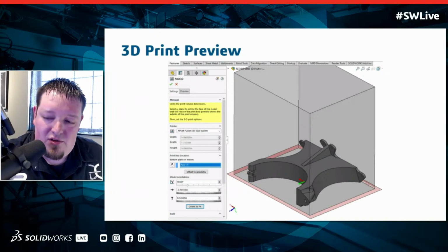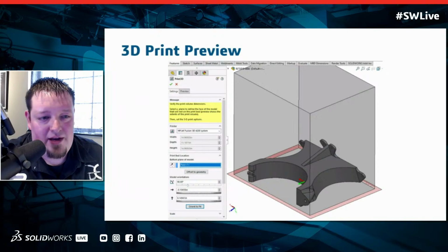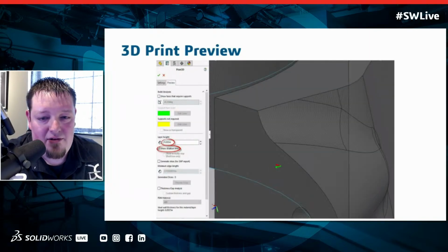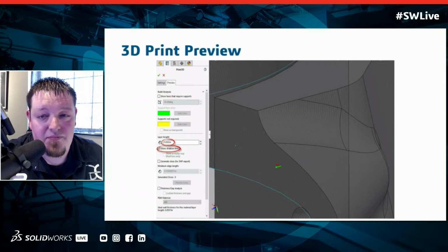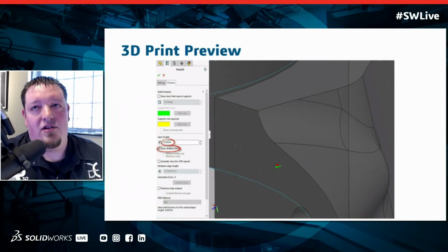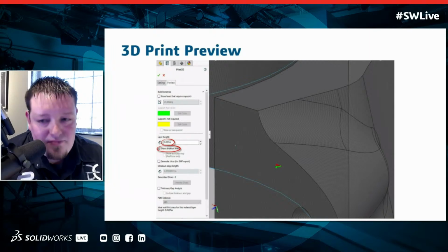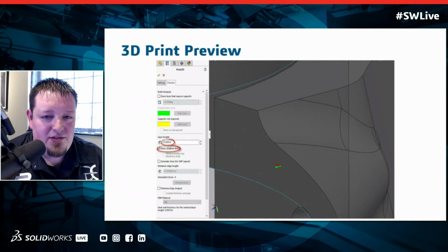There's also a cool tool in here that kind of visualizes what your layer lines are going to look like. So like, for example, MJF, it's 3,000 layers, which is what this is set to right here. So it's super fine layer lines. Like, a lot of times you can't even see them in these parts. But FDM, it's 10,000 or maybe even 13,000 layers, which are going to be very aggressive and heavy layers. So you might be trying to minimize the appearance of layer lines on certain surfaces.